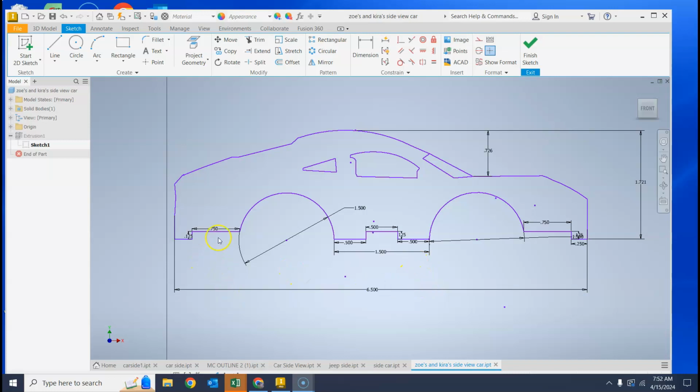One tip, you want to actually remove your dimensions from the car as much as possible. And you want the smaller dimensions to be closer to the car, not farther away, because when you put the smaller dimensions farther away, lines cross. So I'm going to take this sketch that's very good and clean it up a little bit, just for the sake of clarity. So again, as much as possible, you want to take dimensions off the sketch, okay? And you want to remove unnecessary dimensions.